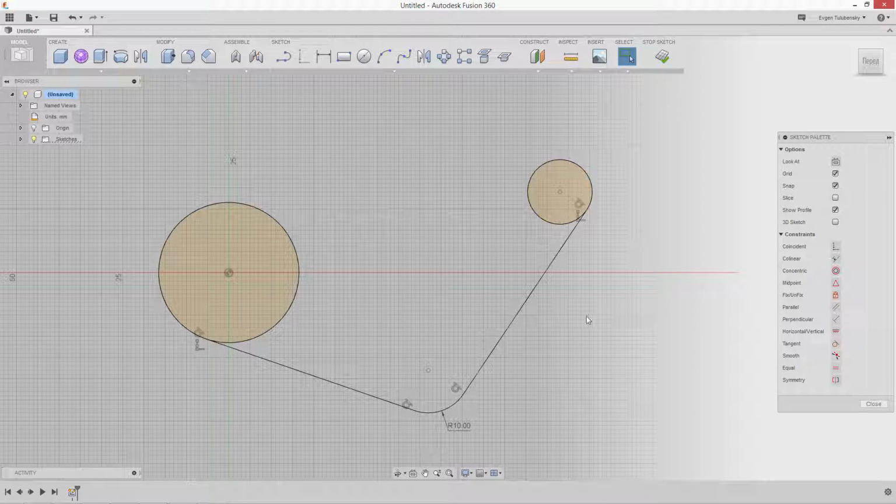Select Sketch, Line. Select the left circle as shown. Hold Shift, then click near as shown. Hold down the left button on the endpoint of the line and drag to create an arc. Click again. Click on the right circle. If you make a mistake, just feel free to delete the lines and try again.